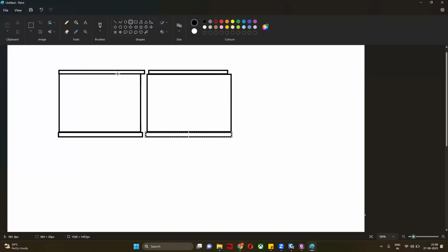Now we want to join these two plates. Very simple, I'm telling you. We need to provide what generally you have seen, or everyone knows. We need to join the webs. So the web will be joined like this, and there will be a bolt here. And if I remove the web, then you need to join the top flange like this, and the bottom flange like this.